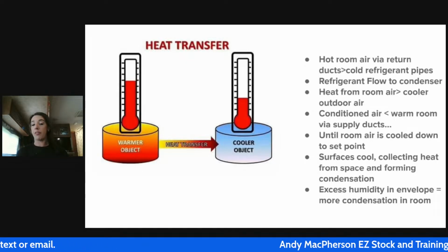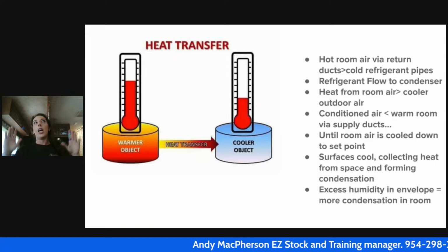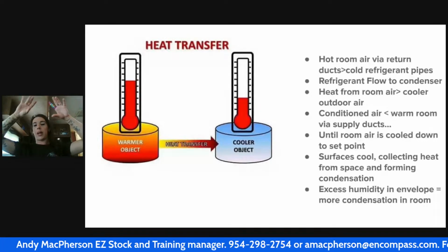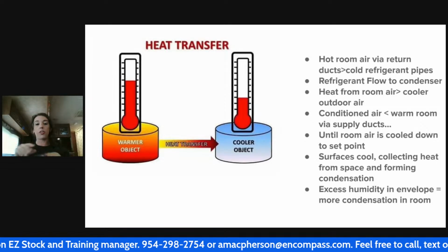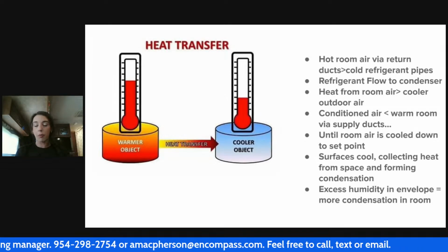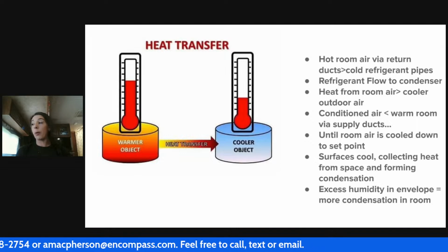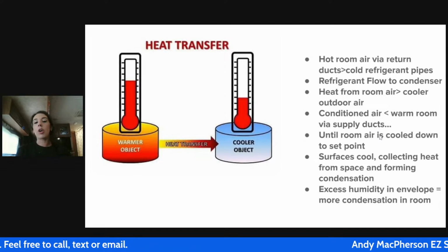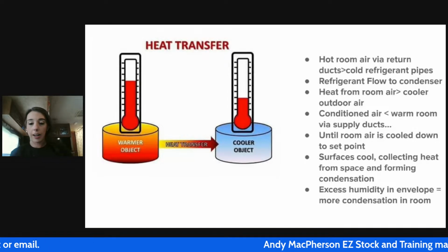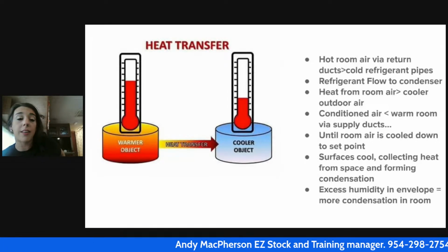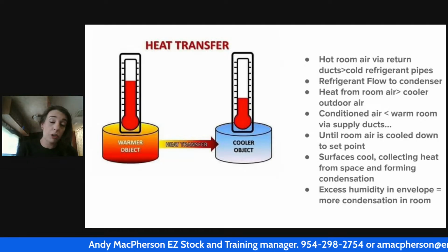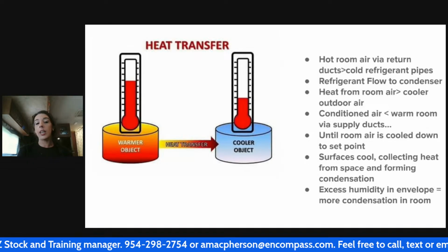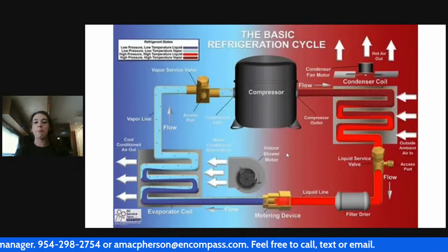running long enough to dehumidify, that's when you'll see supply registers, or even sometimes a return, more typically the supply. You'll see lots of condensation on it. You'll see black mold forming. You'll see growth forming throughout your ductwork. You'll see that your windows are fogging up every time your AC kicks on and off. These are all signs that you are not conditioning correctly, and there are many reasons for that. Some are, again, the envelope, and some could be the unit. But those are things we need to watch for, because if a unit is running, it is dehumidifying, or it should be anyway.